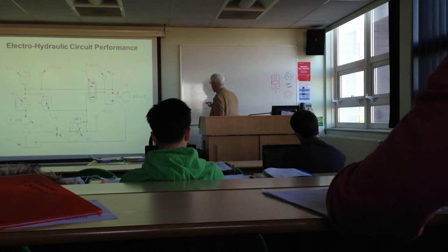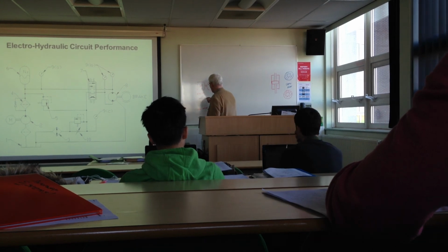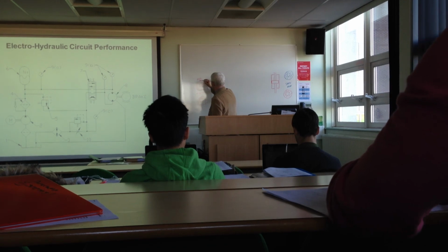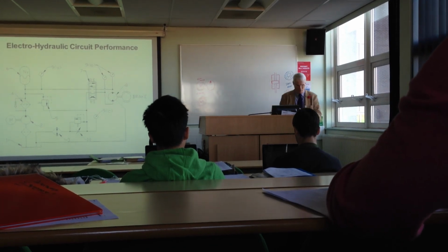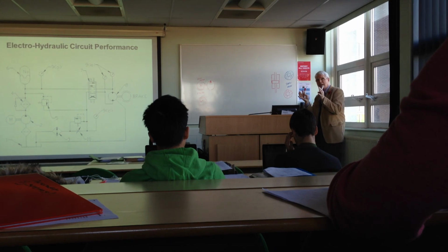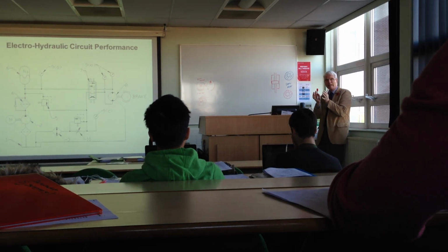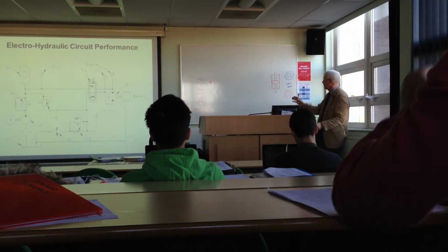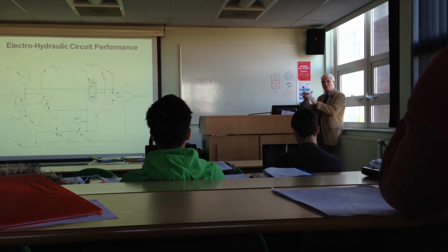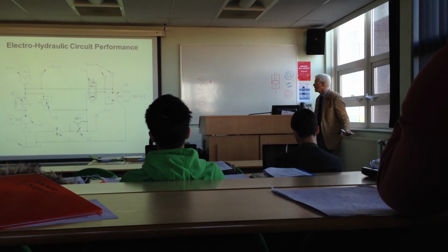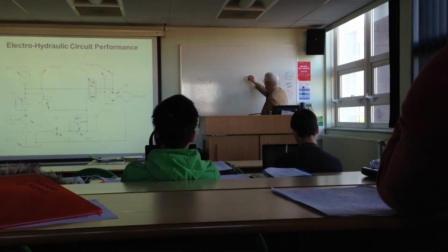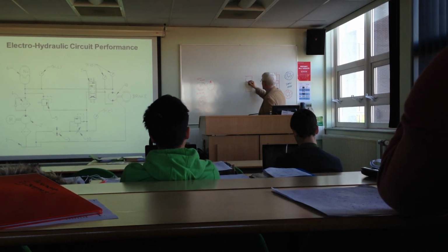Let's try and change these the other way around. So that's an engine, but the electric motor, so we've got electric motor. So we're now actually thinking of a little power pack where we've got a little electric motor driving a pump, controlling a ram, all pretty well next to each other. The ram is going to be controlled by a valve because we need to be able to have three positions